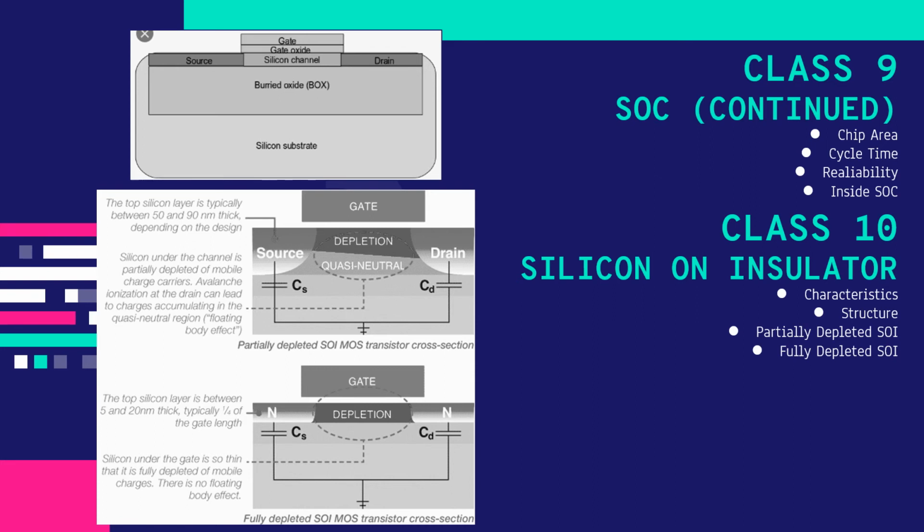The area available to the designer is a function of the manufacturing process technology. This includes the purity of the silicon crystals, the absence of dust and other impurities, and the overall control of the process technology. Other impurities may get added when manufacturing. Improved manufacturing technology allows larger die to be realized with higher yields.